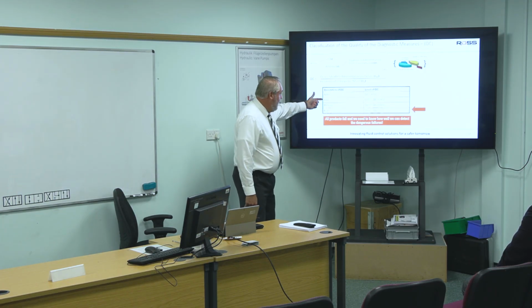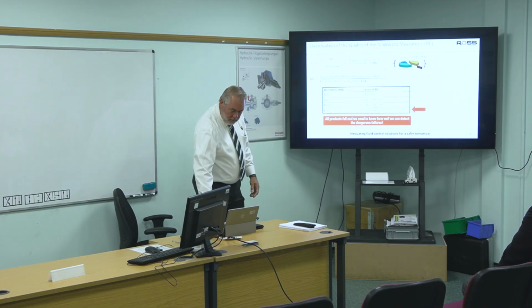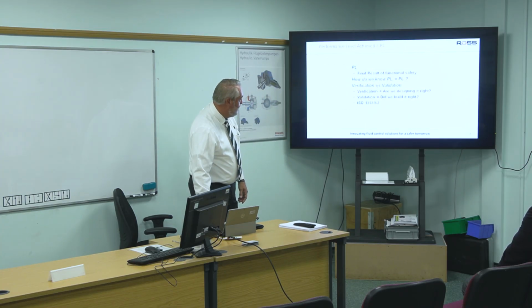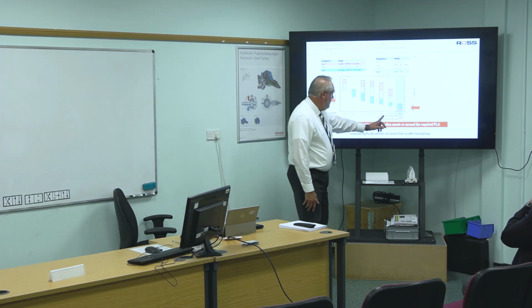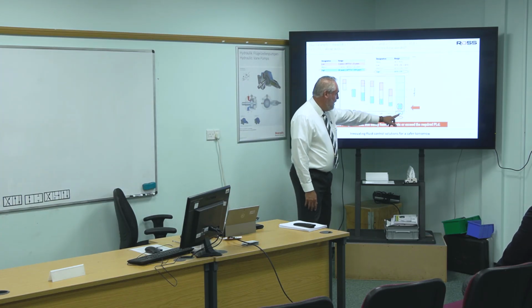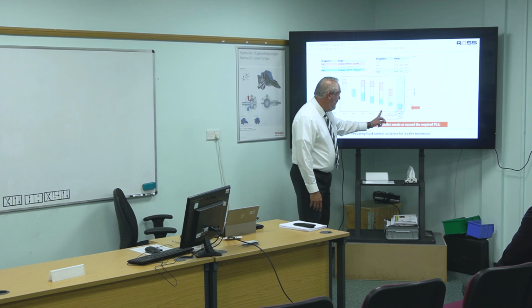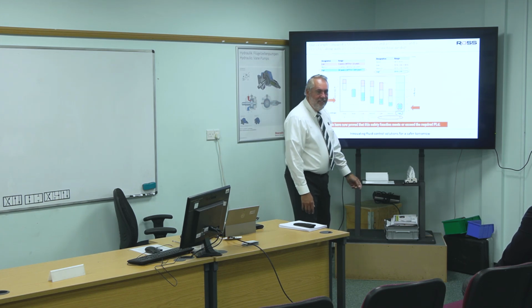So it should be low diagnostic coverage, not high. They said, okay, I had high diagnostics, 99. They actually had low. And if we're low diagnostic coverage with a Cat 3 structure, if I was trying to meet PLE, I'm not there. I'm only at performance level D.